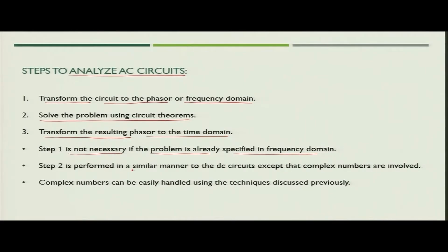The second step is performed in a similar manner to what we did in case of DC circuits. The only change is that here, instead of the real numbers we used in case of DC circuit, we will use complex numbers for AC circuit analysis. Now, the complex numbers we can easily handle, because we have already discussed how to deal with complex numbers when we were discussing phasors and other fundamental theorems of circuit analysis.